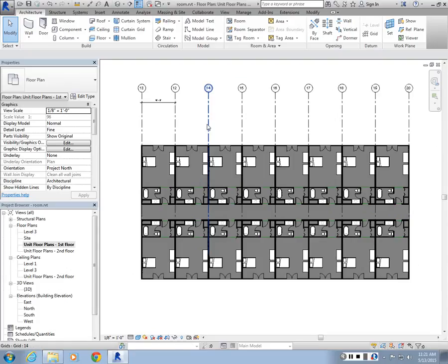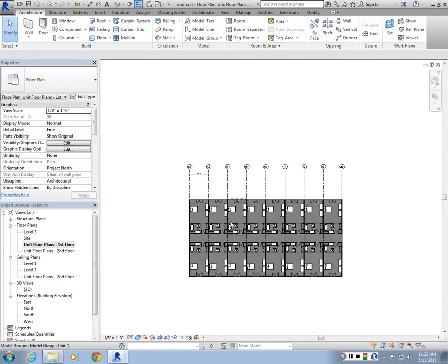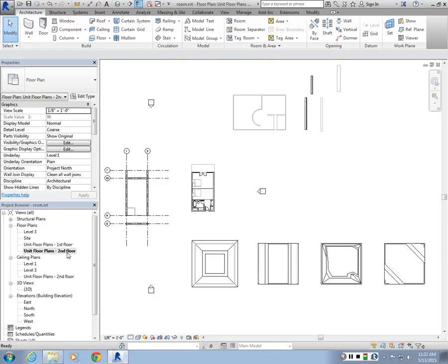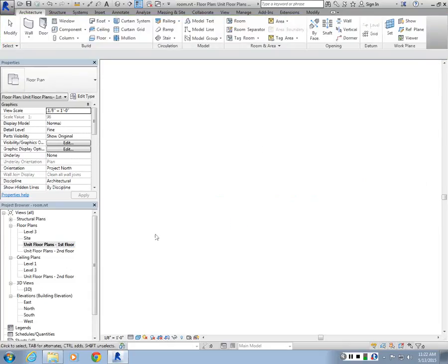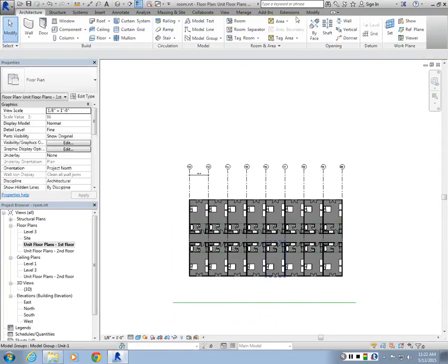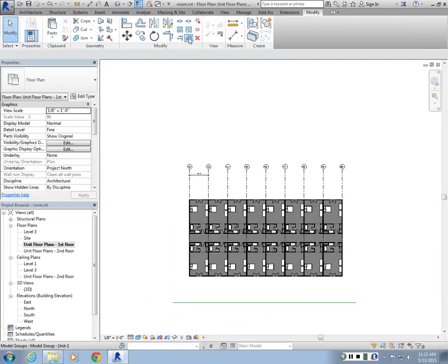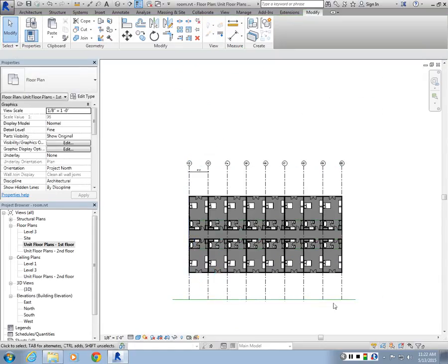Okay, so this is basically my floor, and then I can do the vertical copies as well, right? So let's say we want to have a few levels of this. First off, let me extend the axis lines. So I'm going to create a model line and do trim extend multiple elements. So I'm going to select this line here. We can extend this. This has to be manual. Oh, they actually come all together. So you can extend the axis lines.